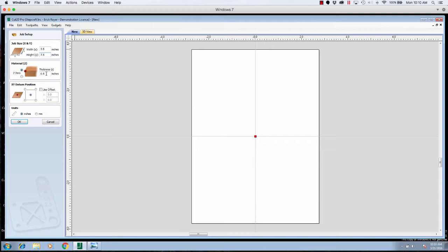Now, the board I bought was 3/4 of an inch thick, but I ran it through my thickness planer because I made one blank to test the size on the wall at 3/4 of an inch, and it didn't look right. For 5.5 inches square, 3/4 of an inch just was too thick. So I ran it down and planed it to exactly 0.5 inches, or 1/2 inch.